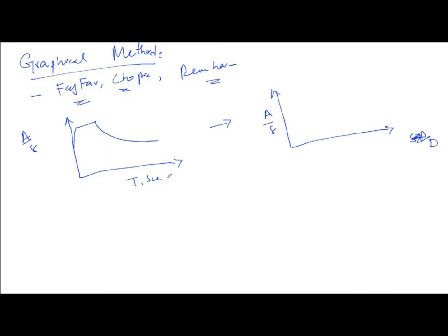So what is happening is that at every vibration period value, the acceleration is converted to displacement by using the pseudo relation. So D is equal to A divided by omega_n squared. So the relationship looks something like this.